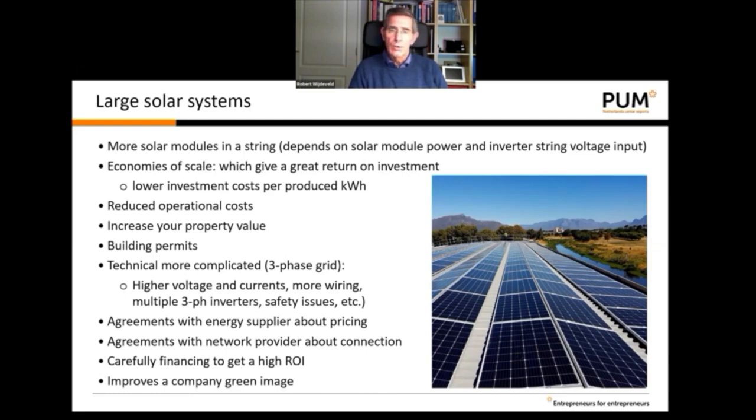It's technically more complicated. You are connected to a three-phase grid. You have to deal with higher voltages, higher current, more wiring, multiple three-phase inverters, and there are also safety issues you have to take care of. Again, you need agreements with the energy supplier about the price, and agreements with the network provider about the connection.